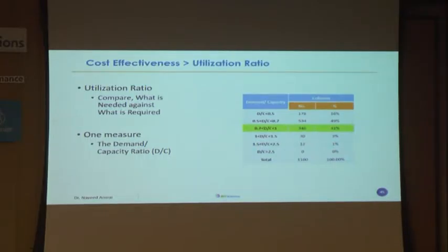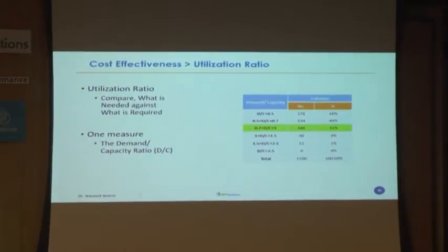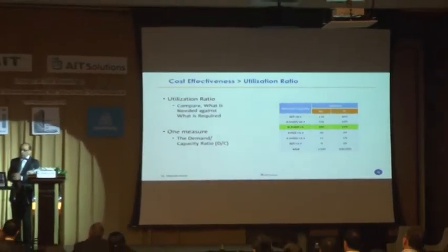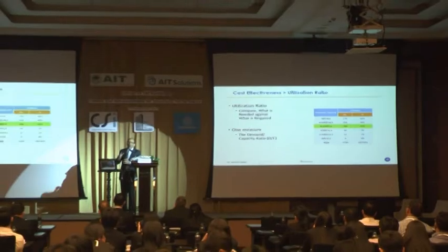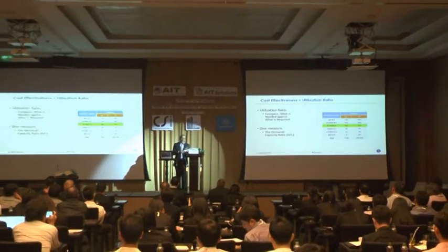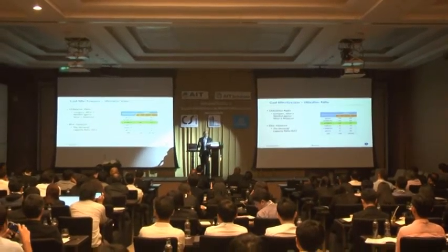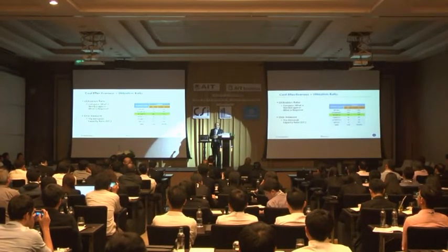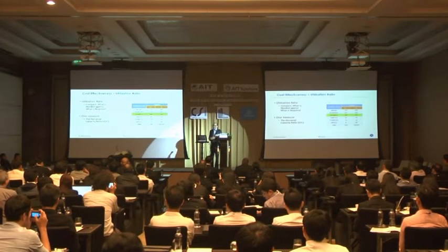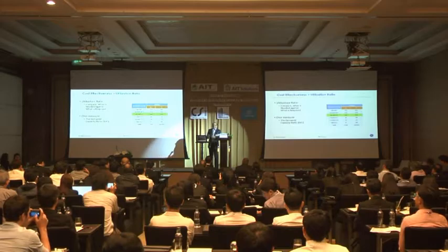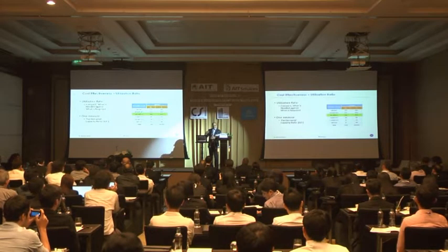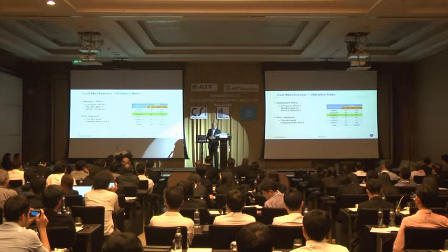So one way to look at it, whenever we finish our design, we can do some kind of a capacity ratio check or utilization ratio check on members, on different demands, rotation, ductility, whatever performance criteria we set. We check and we see, okay, we are getting about 60 to 70%, which is pretty good. And if not, then we can improve the design.